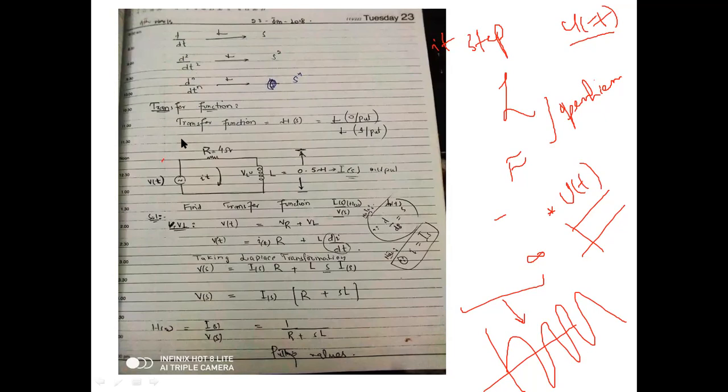Okay, now transfer function. What is the transfer function? Transfer function is the Laplace of the output variable over the Laplace of the input variable. Okay, so output and input may change from circuit to circuit. It depends upon the given values. So the Laplace of the output quantity over the Laplace of the input quantity. The Laplace version of output and input is necessary. Okay, output or input alone is not the transfer function. Laplace of the output divided by Laplace of the input is the transfer function.